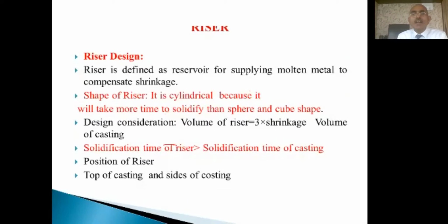Why? Because the volume filled in the cylindrical shape will take more time to solidify than a cube or sphere shape. And the basic science involved is that we should ensure the riser is designed in such a way that the riser metal should solidify last. First, the casting metal should be solidified. And if shrinkage occurs, metal will come from the riser and you will feed it.